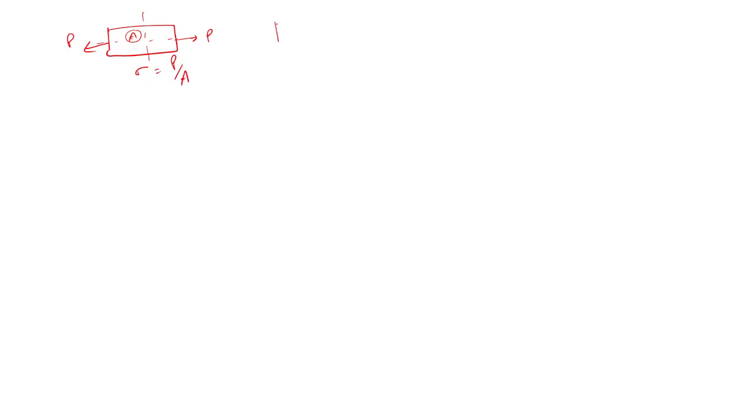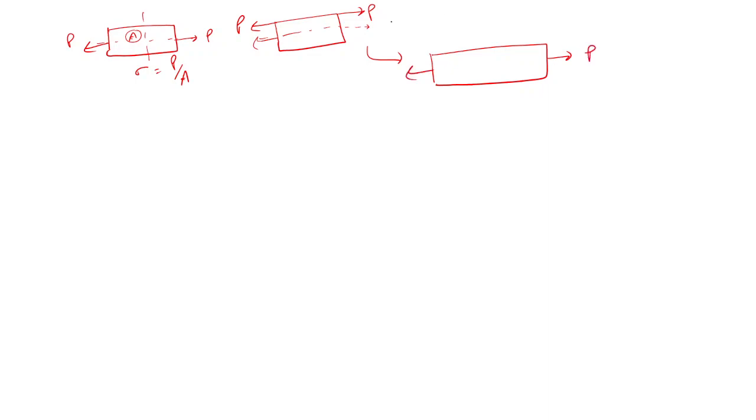And if it is not passing through its center line, let's suppose some force is passing from here, first you have to shift that to the center, and an equivalent amount of moment we can apply, and then we'll proceed. For example, here we will shift this force P to the center, and let's suppose the diameter is D. So what will be the moment due to shifting of this force? P into D by 2, right? This moment P D by 2 would be there.